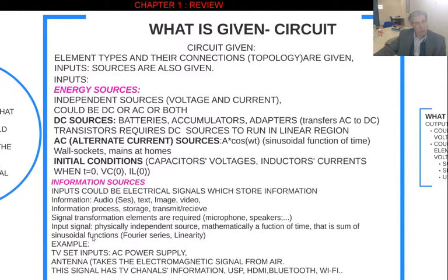And this summation fits linearity. In linear circuits, if you have more than one source within the system, you can find the solution for each source. When you add them up, you find the solution when all of these independent sources are included in your circuit. That's linearity. So it fits that linearity, because we are going to see the summation of sinusoidal functions, as any function could be written in this form.